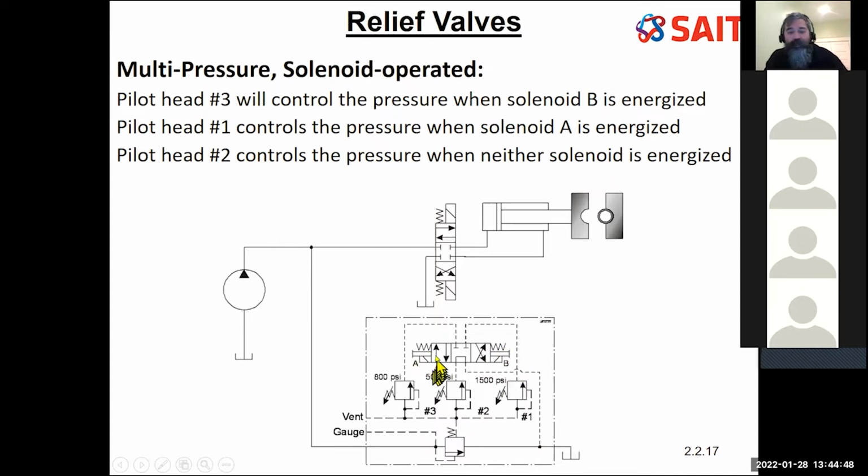These are my electrical symbol for a solenoid, well, my pneumatic or hydraulic solenoid, as opposed to what we had in our MEC 205 electrical drawings. Neither one is activated, so the springs hold it in the center. If I activate A, push this position over, the fluid coming through will go through there, if I remember correctly.